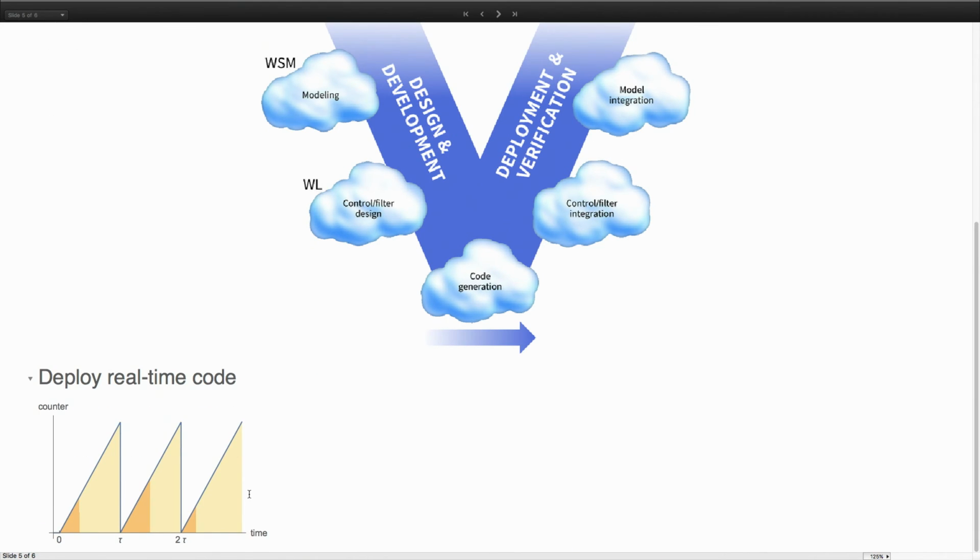And another advantage is it generates hard real-time code. At each sampling instant, the microcontroller is doing a bunch of tasks, and there is no control over how much time it will take to complete the tasks each time. After that, it is essentially idle except for any interrupts it has to service. But this code does not depend on how long it takes. At each sampling period, it exactly starts doing the whole sequence again. So we enforce hard real-time constraints in this.